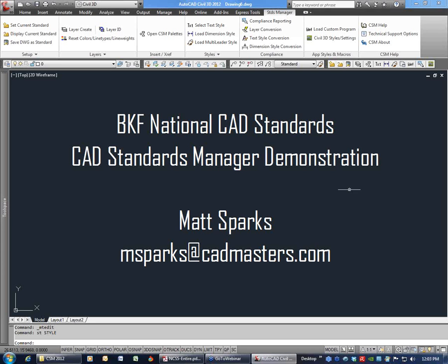And the biggest thing that I do want to point out is our software is accessed either by a toolbar or a ribbon. For those of you who might not be familiar, this is the new interface that AutoCAD uses. There should be a Standards Manager tab in there for every user. And if this does not appear in your ribbon tab, you will have to type in CSM at the command line. It's a command that reinitializes. And again, if that doesn't work, then obviously we have to get hold of Mark and get it installed on your machine. So the first thing you want to try, if you don't have it installed on your 2012, is to type in CSM at the command line.